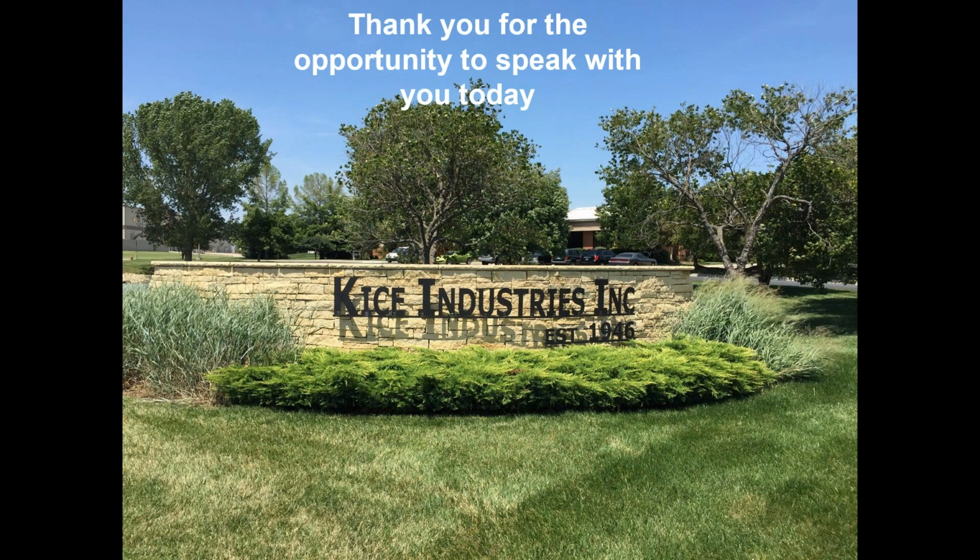No, I would say it would be the opposite. It would be the bags popping at that high PSI. If you pulse the air through this filter bag every 10 seconds, you're eventually going to wear through that filter bag, as opposed to if you pulse through that filter bag every 30 seconds, it's going to take a lot longer to wear through that filter bag, just based on the force of the air against it. It's not necessarily due to the dust buildup on the outside of the filter bag. Too frequent pulsing would damage the bag by too frequent high pressure pulses punching that bag from the inside.